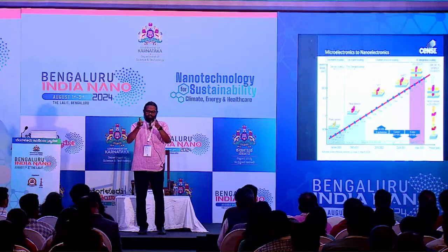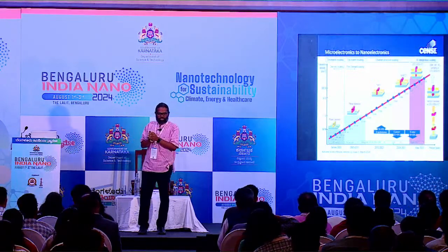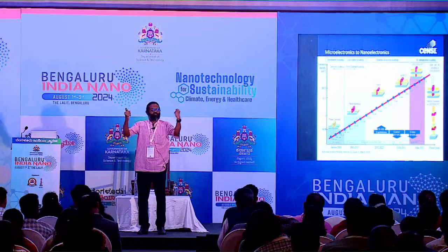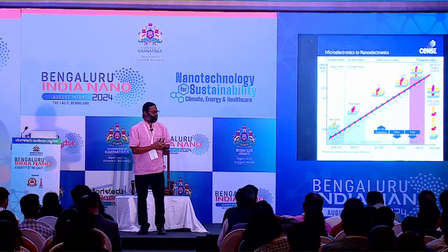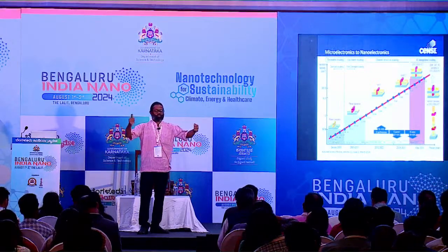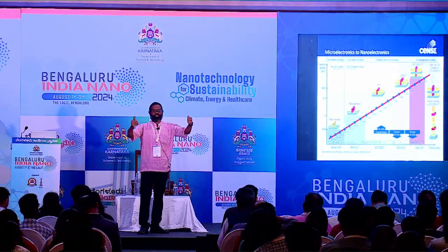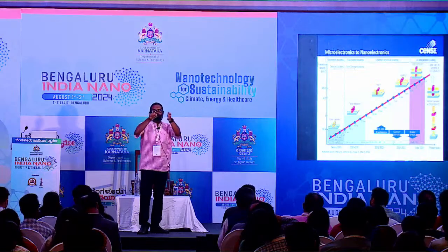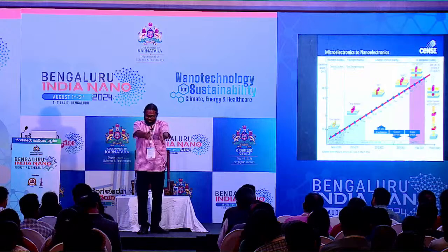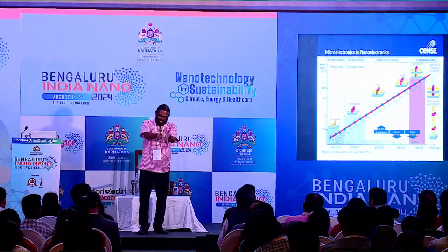When the size of these transistors were becoming smaller and smaller, you have to apply enough potential to stop the leakage, right? So that is the major problem that we had between the source and the drain. The charges are moving from source to drain, and you need to make sure that they don't leak, okay? So that's where you put the gate.